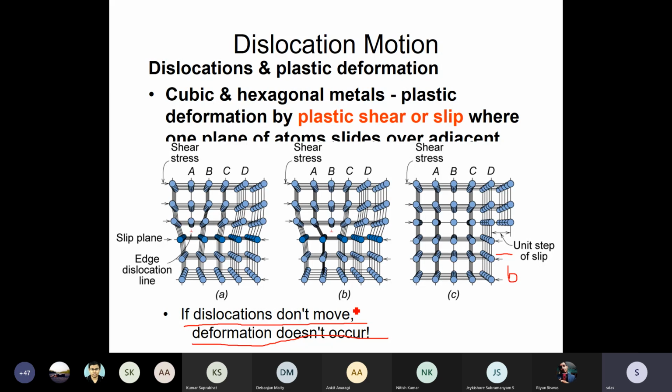It obeys Hooke's law. Now if I stress it above the yield point, dislocations start moving, and you create a permanent deformation, which is called plastic deformation. If you remove the load, the elastic component of the deformation is restored, but the plastic component of the deformation is not restored. It becomes permanent, and that is the strain in the material.